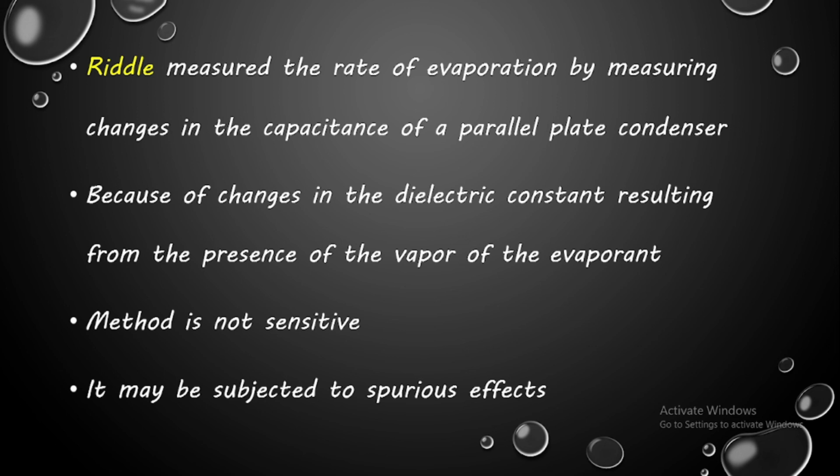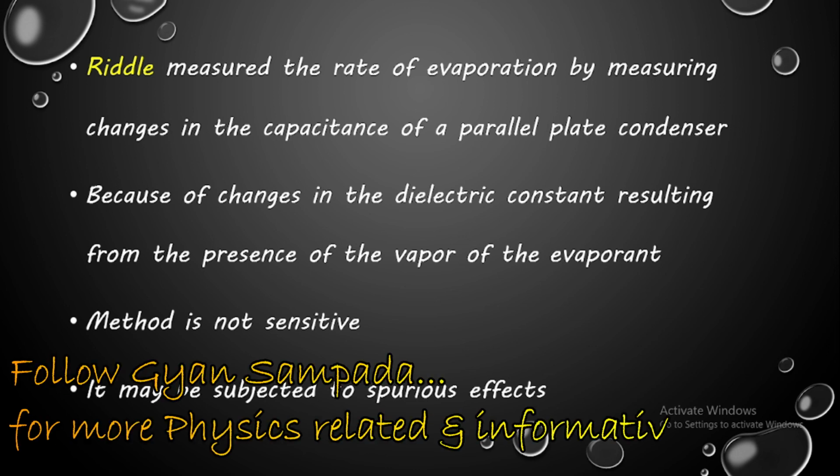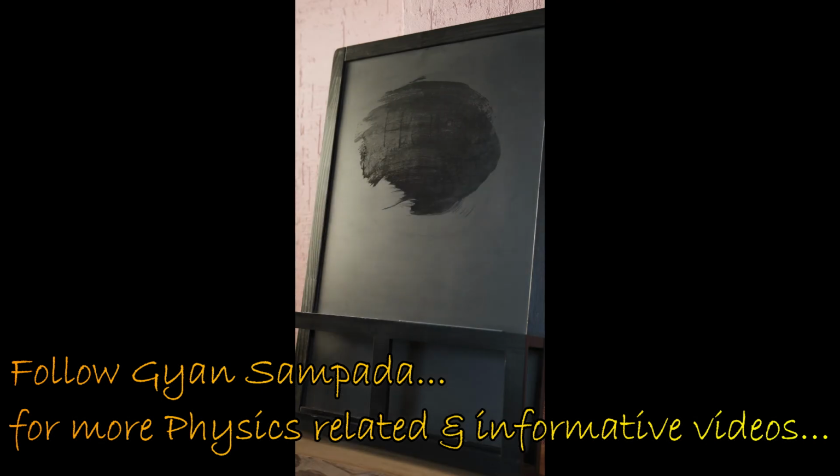So these are the two main methods which we use in order to find out roughly or accurately the thickness of any thin film. So in today's class we saw the first method, which is the electrical method, under which we studied two approaches. One was using the resistivity measurement and the second was using the capacitance measurement, and we understood how we are going to find out the thickness with respect to these two parameters, that is resistance and capacitance.